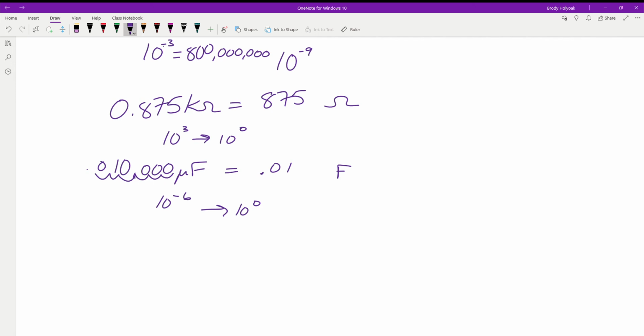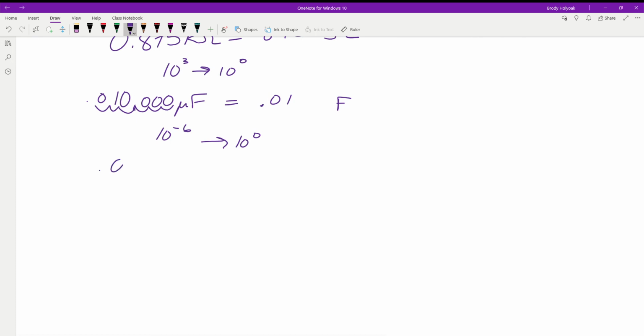This is what you'll see in capacitors. There'll be times that they're going to be rated in microfarads, and we have to determine, it comes up. Another common is you'll see 0.001 microfarads, and we want to know how many nanofarads that is, just to give us a comparison number, an easy one to put in. Because this is kind of hard to look at because you're micro and you have a decimal value. Why not convert it into a whole number in one of our engineering prefixes? Yep, 1 nanofarad, because we're going to move this 3 decimal places.